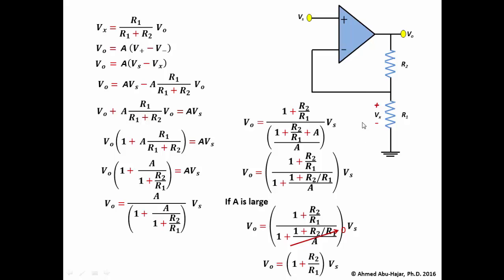But what's important about this perspective, the way we showed you this circuit, is that we have two important aspects from it. The first one is we understood that we fed the output back to the input, and in this particular circuit we fed a portion of that output into the input, and we have to force the current into the op-amp to be 0 or very small, so that it is negligible. And this is part of the designer who designed the op-amp. The people who designed this op-amp circuit need to guarantee that the current is very small.